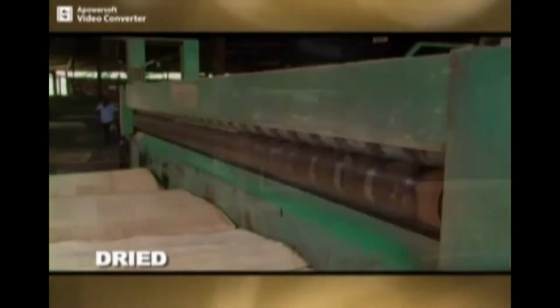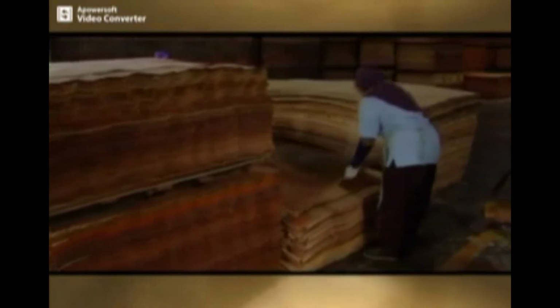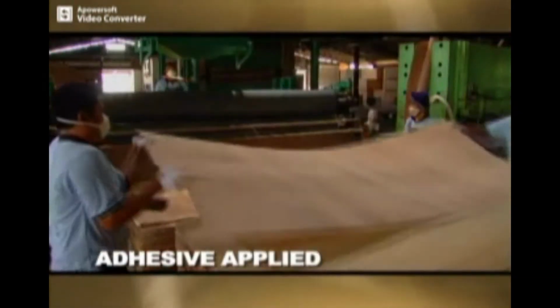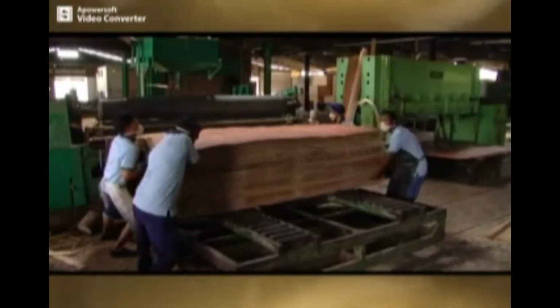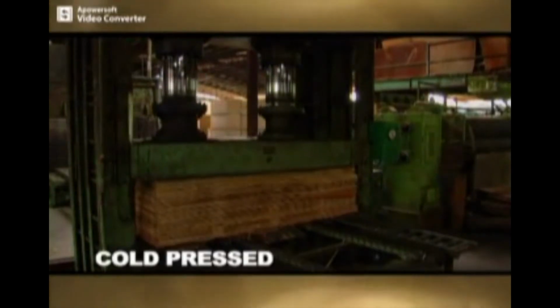The wet OPT veneers are then dried at the veneer dryer. The next process is lamination of veneers into panels. Firstly, the dried veneers are applied with thermosetting adhesive in a cross-ply layup. Then, the laid-up veneers are transferred to the cold press to ensure that the adhesive is evenly spread.